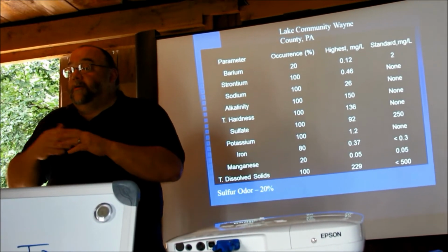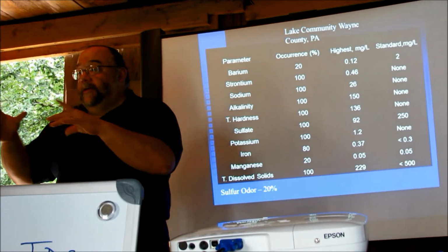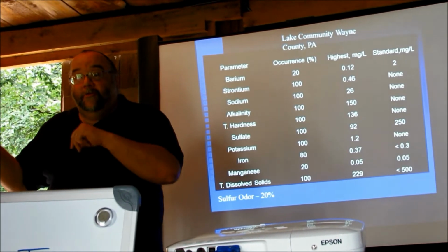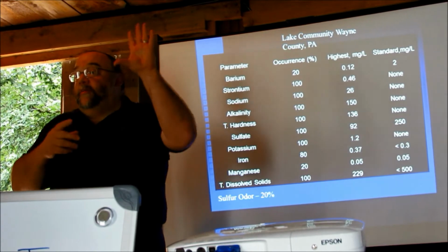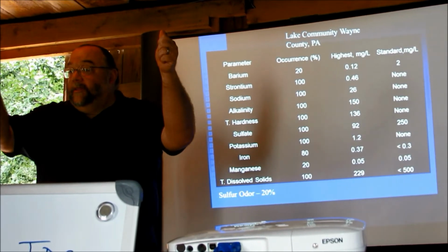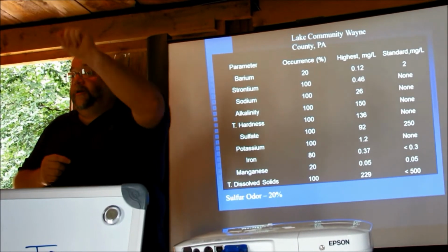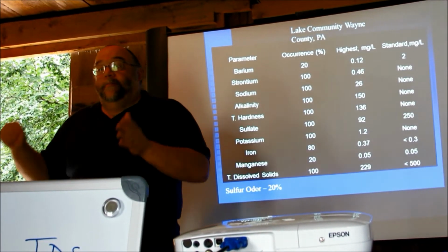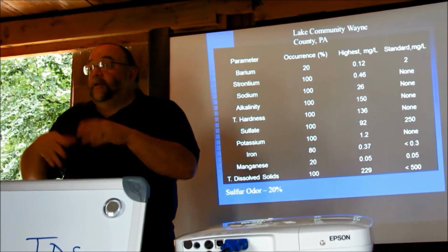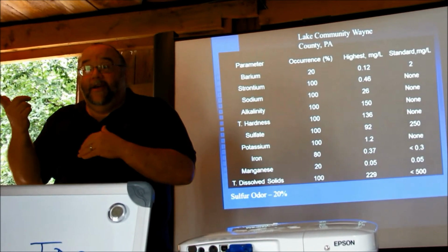Or the other option is, if you have multiple conductivity meters, two or three of them, you say this is the one for streams, and you program in the 0.5 ratio for freshwater streams. The other one is for saltwater, and you program into it the 0.9. So that was my second recommendation to them.